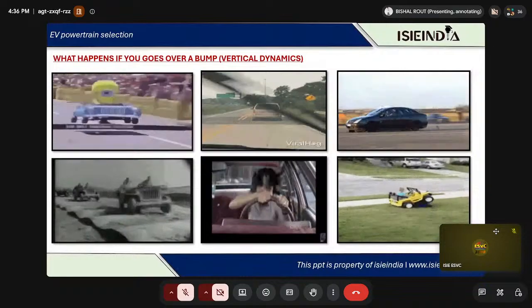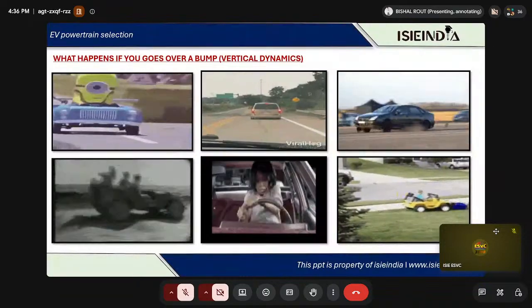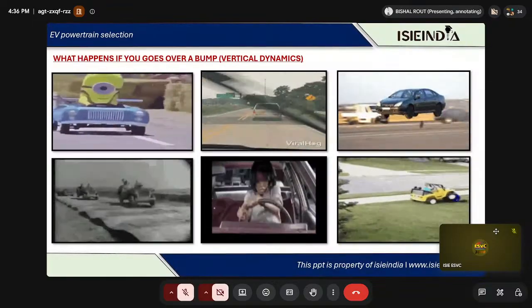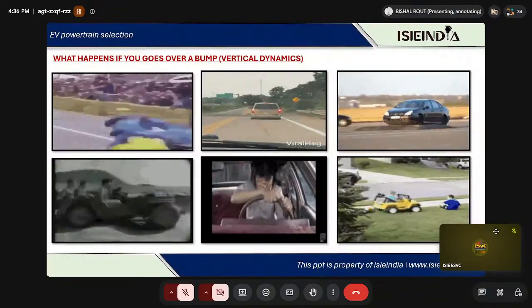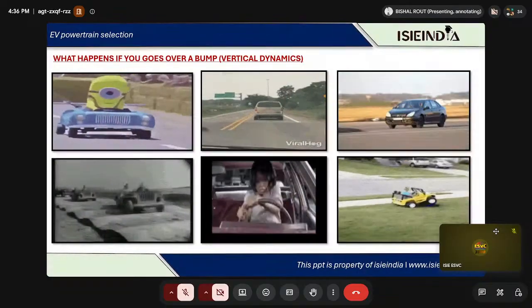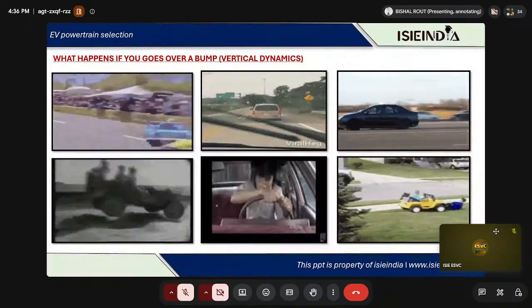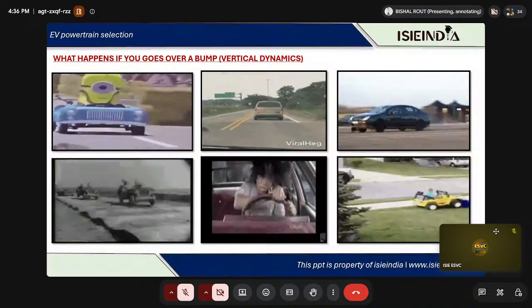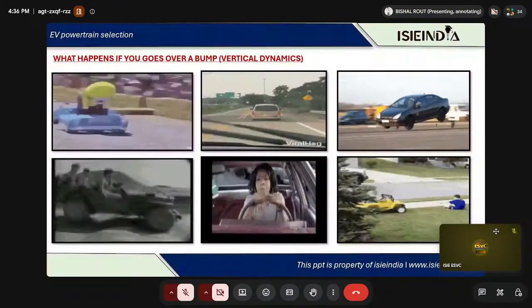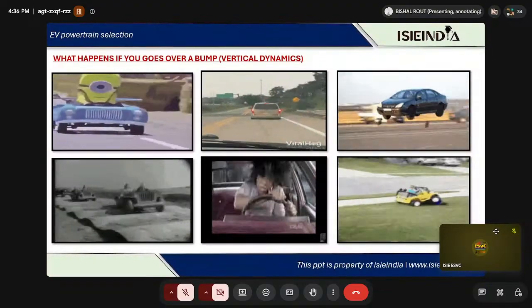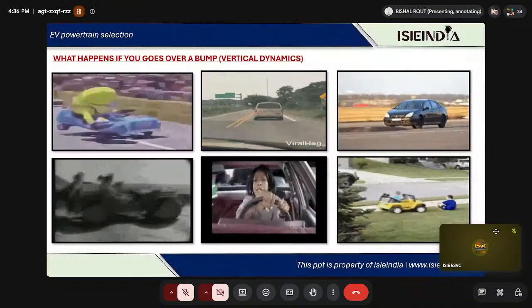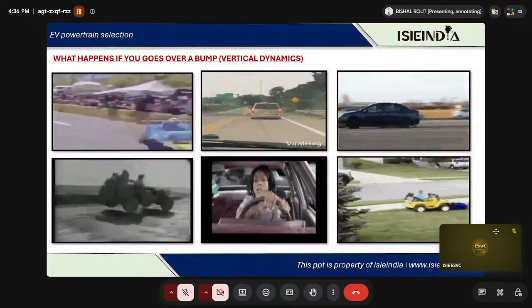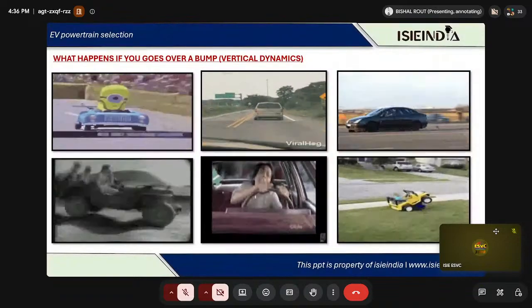We are more focused on the longitudinal vehicle dynamics, basically, right? We'll be more focused on the longitudinal vehicle dynamics rather than other vehicle dynamics like lateral and vertical. Because here our intention is to calculate the torque speed characteristics, and how to store that value inside MATLAB, so that while designing a motor we can use that torque speed value and check, basically, right?